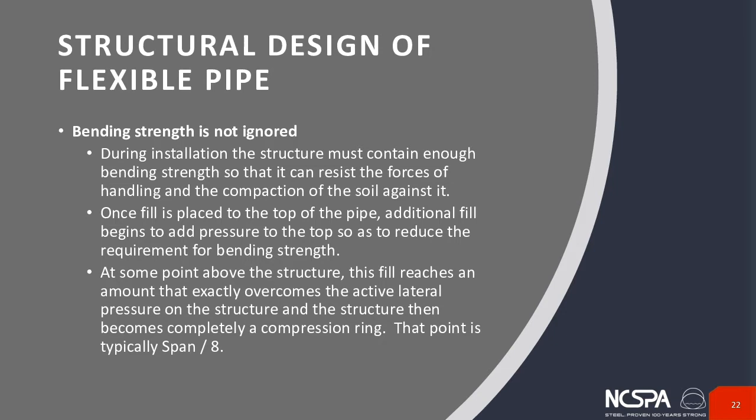But once the backfill depth over the structure overcomes the active lateral pressure that the soil exerts, the structure becomes completely under ring compression. Now, that depth of cover is typically span over 8, and that's often considered the minimum cover for normal live loads.